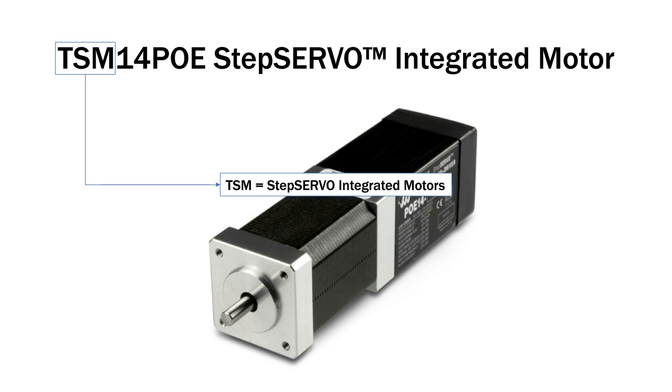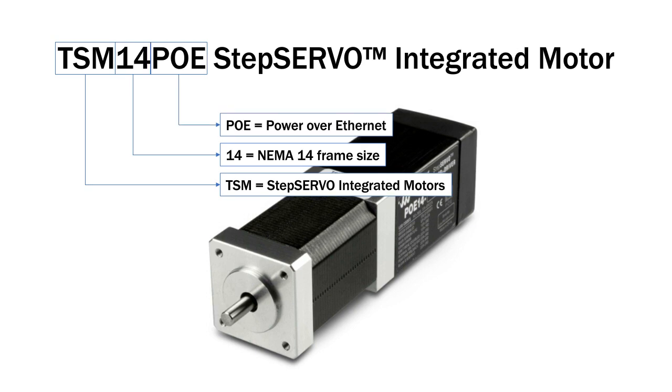It's still a fairly low-speed animal. It doesn't give us thousands of RPM of speed, but it does give us some other nice benefits, which I'll show in a second. So TSM refers to a whole family of step servo integrated motors that we offer, i.e. closed-loop stepper integrated motors. And the TSM14 PoE is just part of that. 14 is the NEMA 14 frame size, and PoE, of course, is power over Ethernet.